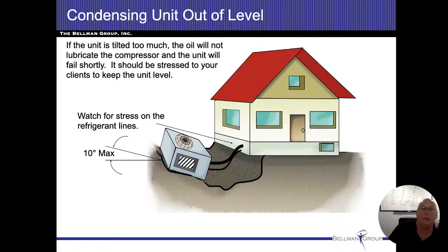So I know there's test questions about compressor cabinets being level, all right? In all reality, yeah, they should be level. I really don't make a big deal when they're not. This side is telling us we can go all the way up to 10 degrees, and it's not going to be that much of a big deal.